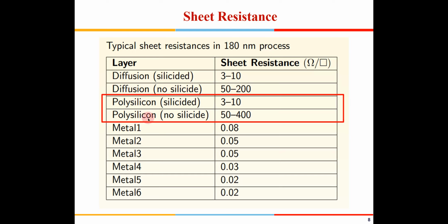sometimes we find it easy to interconnect the gates with polysilicon itself. Even if they are very far off, you can do that, but you have to keep in mind whenever you are making interconnections of, say, two transistors which are close to each other, you can interconnect them with polysilicon itself, with the gate material itself, like I think we did in the VLSI classes about layout. I discussed in detail in one class, where the gates can be interconnected with the gate poly